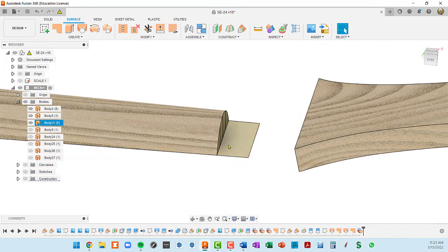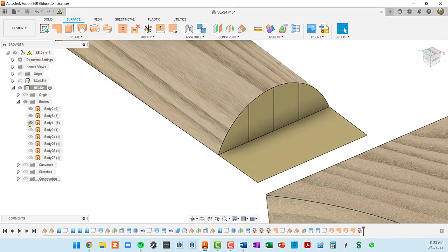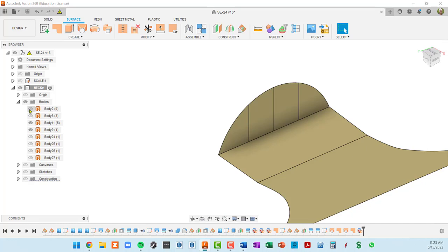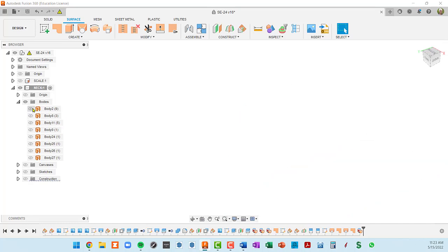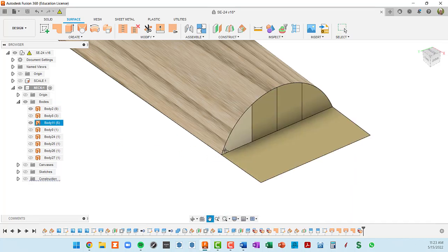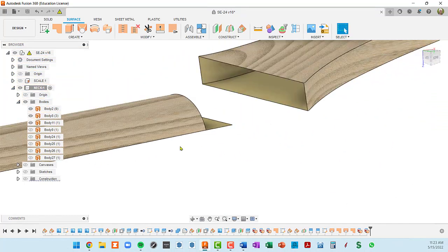That one looks fine. Now this came in. This could be a problem here. Let's see. Which was the body? Okay, it was this one. So let's go back just to this body. Nope. Yes, okay. So now I've got two bodies enabled here, and these surfaces are going to have to go away. So I'm going to click and shift click on those four surfaces and take those away. And now I think everything is set up to go.